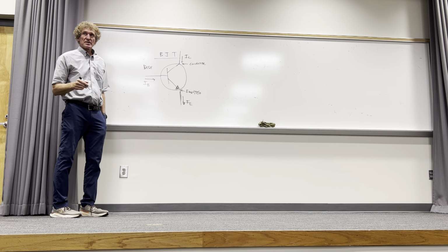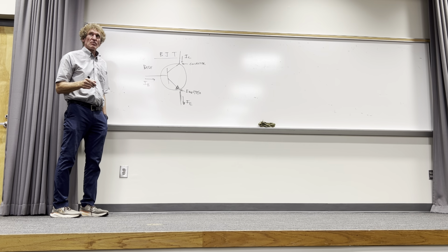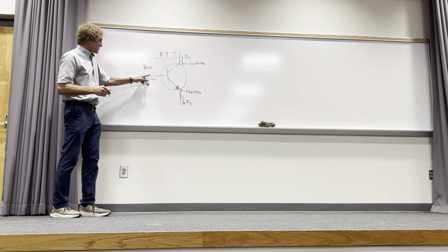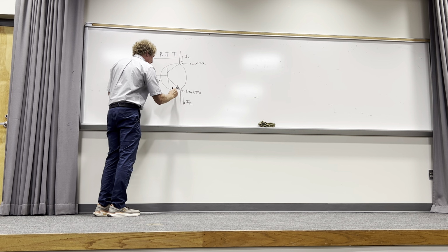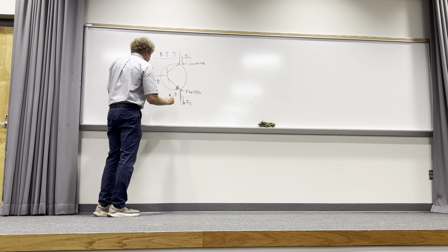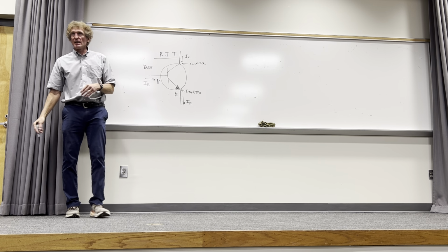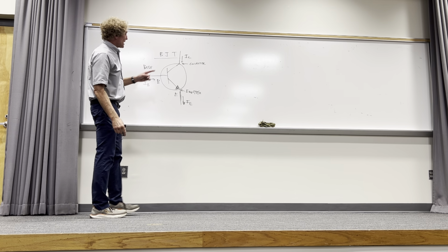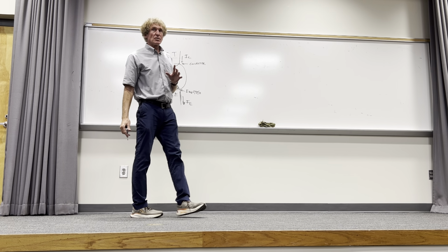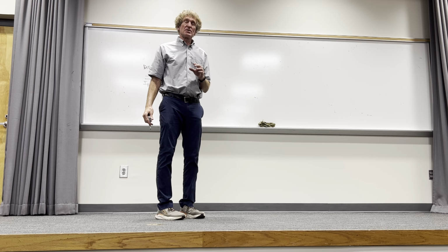And this is a voltage controlled current amplifier. I'm just going to tell you this. The voltage between here and here, this is the base and this is the emitter. So the voltage between the base and emitter, or VBE, dictates the current that will flow, IC. Now here's some important relationships that will be true in what's called the active region.